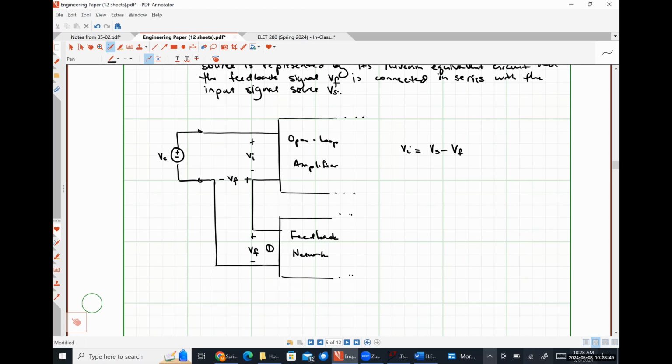If we were to look in and find our input resistance with feedback, what do you think we're going to see based on our prior experience? We connected it in series, so should we boost the input resistance or attenuate it? Boost it. What do you think it's going to be boosted by? 1 plus Ka. Absolutely right.